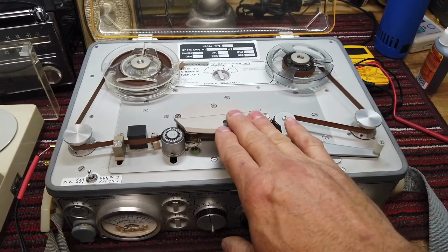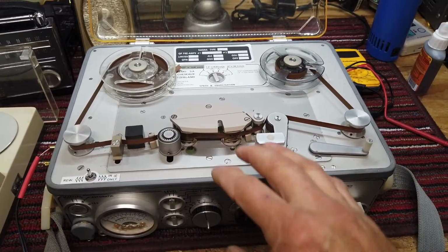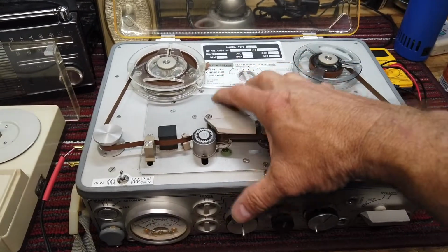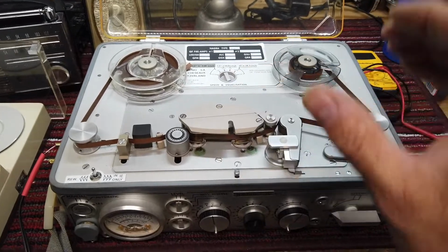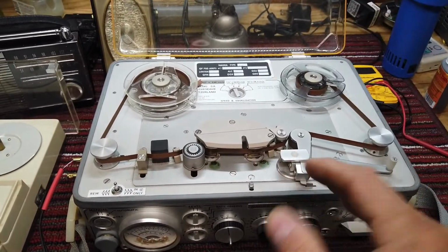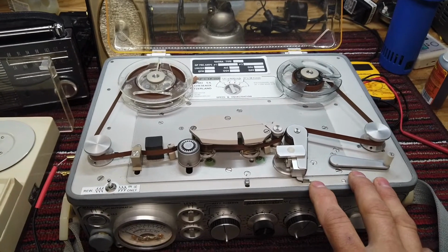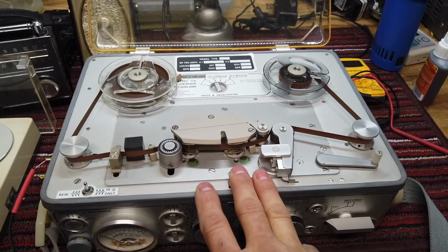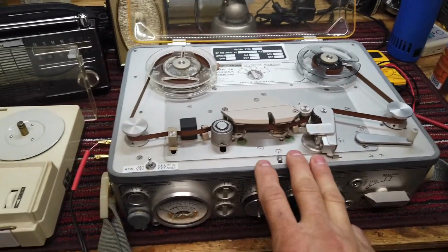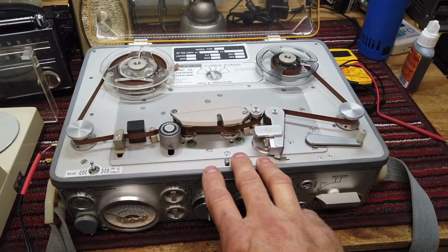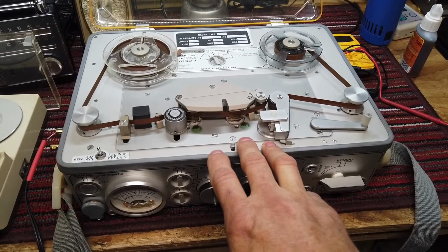So we're going to record a tape, and that introduces wow and flutter into the tape because of the mechanics of the system, and then we're going to play it back, so that doubles the wow and flutter, if there is any, on this recorder and player. So that's the best reference point I have at this point in the study. So I hope that's clear.